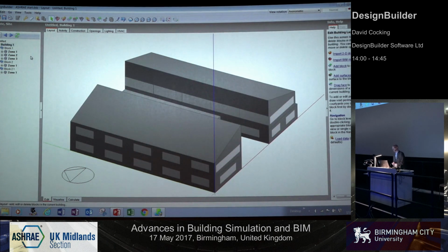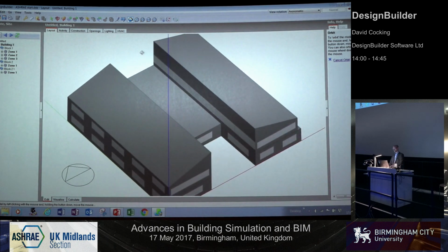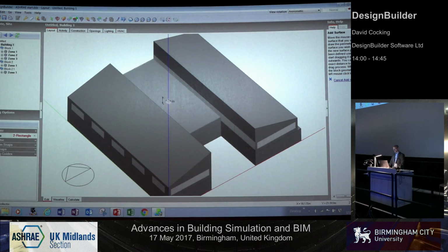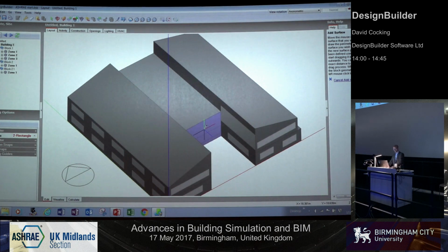Quite often, the design changes through the course of a project, so we may need to update the internal geometry, external geometry. So these geometry tools that we use to create the original stuff, or if we've got a BIM model, we can very quickly and easily use those tools again, just to change that geometry that we've already created. So I want to raise that up by, let's say, 3 metres, and I can just create a 6 metre high centre section in that inner core zone there.